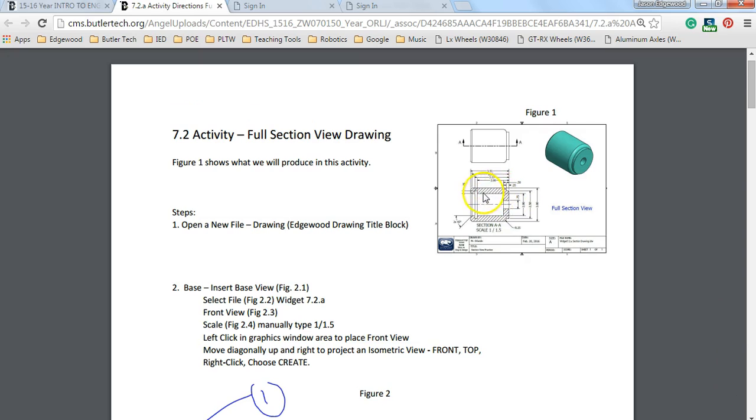This slashed material is where we actually cut through material. On the inside, when we removed part of it, that reveals some edges and lines that may otherwise have been hidden, and now they're not hidden, so we've got some solid lines in here where they might otherwise have been dashed if we had hidden lines turned on.